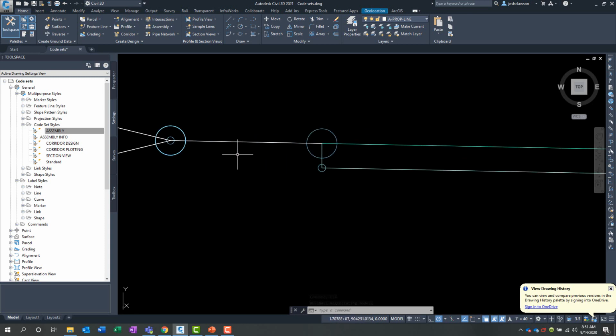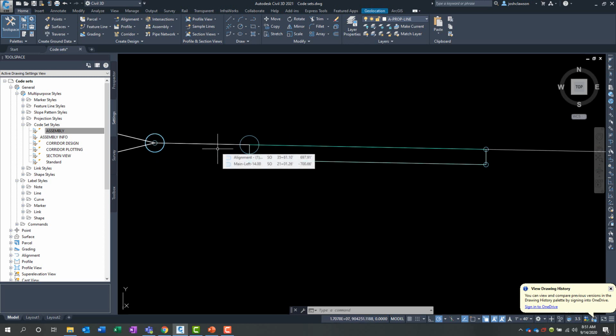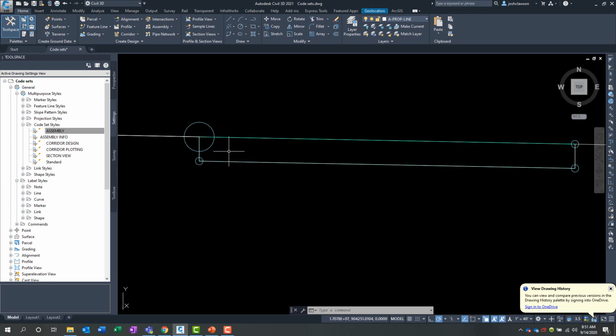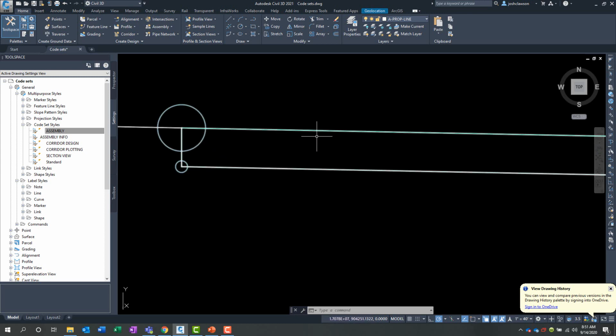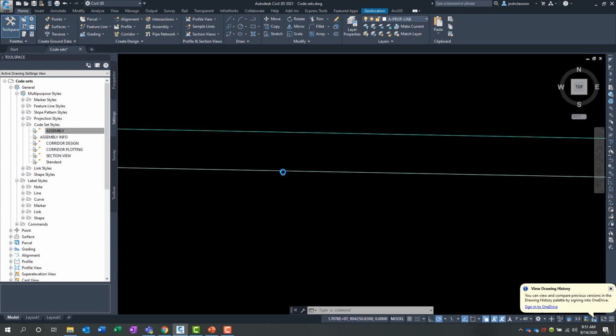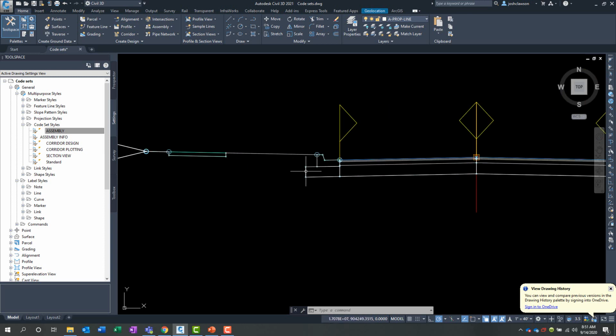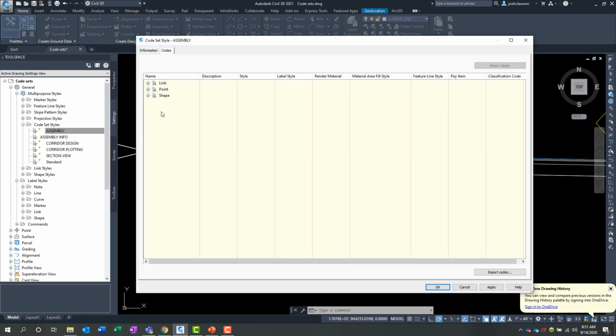And what's happening here is, remember when I said that most subassemblies out there are going to have a top and a datum code. So why is this sidewalk just showing this greenish colored line on top? Well, it's because that datum code is running across the bottom. So I'm going to change that datum code to a no display, and we should see some different colorization here.